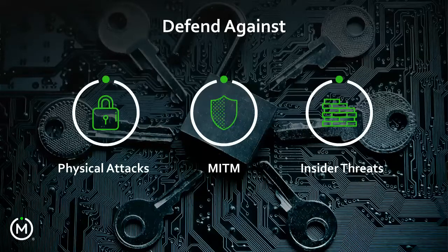The other emerging solution that some silicon vendors you're working with can provide is an encrypted flash file system. So the flash itself is encrypted by the silicon vendor, providing one additional layer of protection. So it's really as a key store or a certificate store that flash comes in handy.